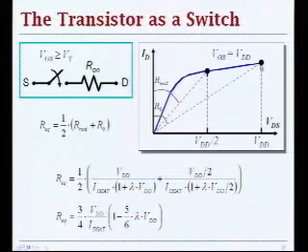So basically, all you care about is where your switching occurs for the delay analysis, because you want to analyze how long it takes to reach the 50% switching point, and you don't care about the rest. So let's assume that you have, for example, a pull down operation, and you start from VDD and you go all the way down to VDD over 2. So to precisely calculate average resistance, you can simply calculate at each of these points and then average out.